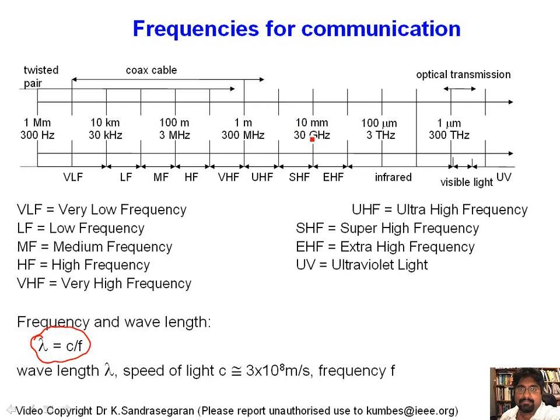So there are good, positive things, because as you move to higher and higher frequency bands, for example, if you have 30 gigahertz, and you take even 0.1% or 1% of the bandwidth, we're looking at about 3 gigahertz of bandwidth, which is a very large bandwidth. Whereas if you take 1% at a lower frequency, like 30 kilohertz, it only gives us something like 0.3 hertz. So as we move to higher and higher frequency bands, the amount of bandwidth that is available also increases.